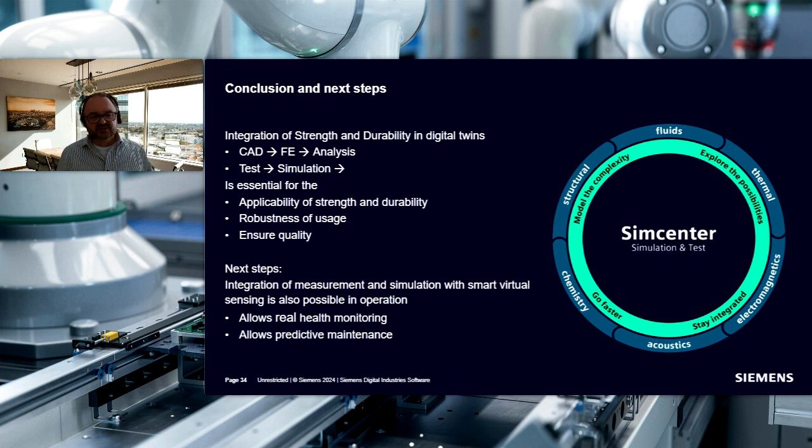It's very important to have it in CAD, finite element, and the durability analysis, but then also the integration of tests. This really is essential if you want to apply it, and also for knowing the robustness. So instead of just looking up some kind of load scenarios from a book or from some kind of recommendation by certification units, you have a much better knowledge of your real loads, and then you can ensure the real quality of your products and not something which is more or less independent from that.